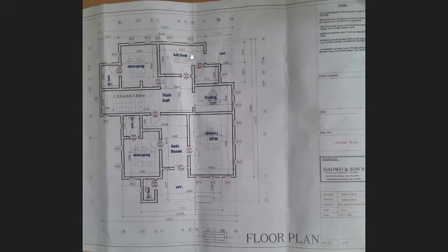And then of course the kitchen: just by the kitchen, there's a straight line here in the anteroom. These two have very similar dimensions, but when you get to the anteroom, there's 2.4 meters of space, and the kitchen doesn't have that 2.4 space. It just continues for about 4.2 meters. So we actually split the anteroom and took that as the structural frame. There's going to be a beam running straight across all the way to the kitchen like this.